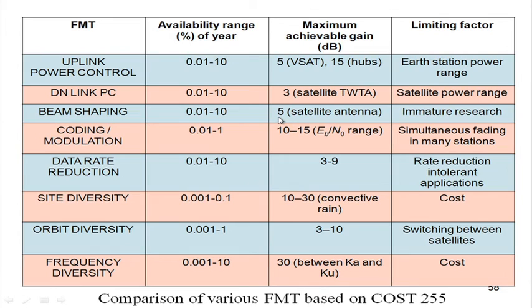You don't touch the power amplifier. In that process you save on intermodulation products or adjacent channel interference, but your problem is that the satellite antenna becomes very complex. Normally these are designed with a complex array antenna with additional phase and amplitude adjustment.